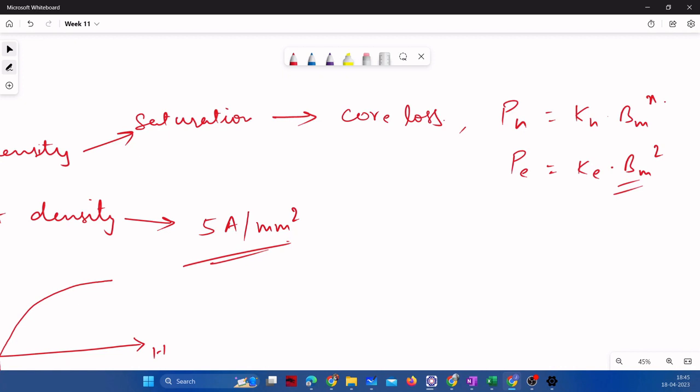So, let me talk about why these are required and where solid wires are preferred. Generally, if you use solid wire, we are operating with alternating current. We have a certain switching frequency and core material. So there are two types of losses, known as skin effect loss and proximity effect loss. Those depend on the skin depth of the conductor.